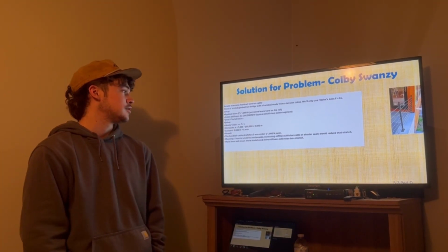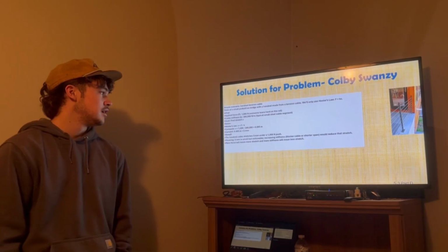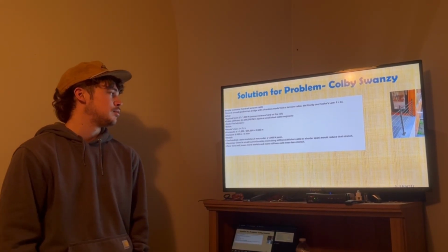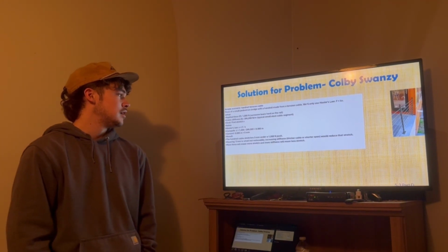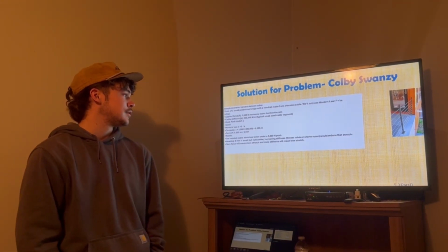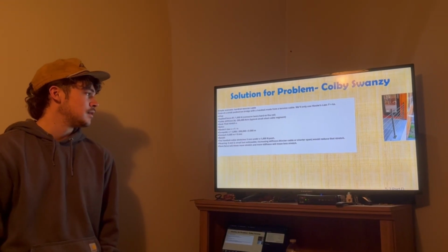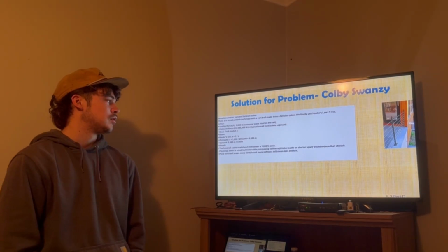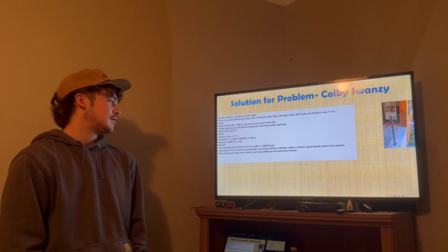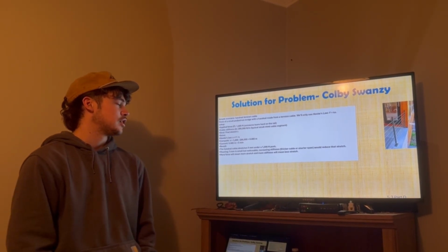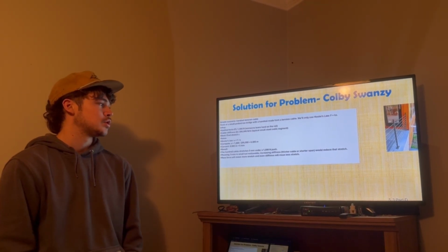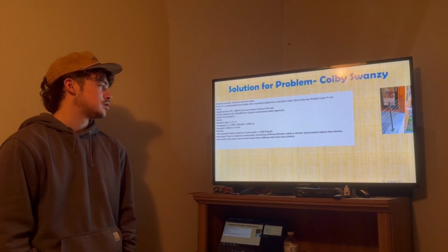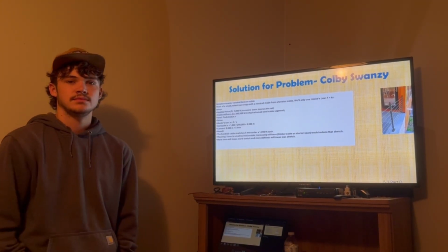Hooke's law: X equals F/K. The compute: X equals 1,000 over 200,000 equals 0.005 m. We're going to convert 0.005 m equals 5 millimeters. The result: the handrail cable stretches 5 millimeters under a 1,000 N push, meaning 5 millimeters is small but noticeable. Increasing stiffness, a thicker cable or shorter span, would reduce that stretch. More force will mean more stretch, and more stiffness will mean less stretch.